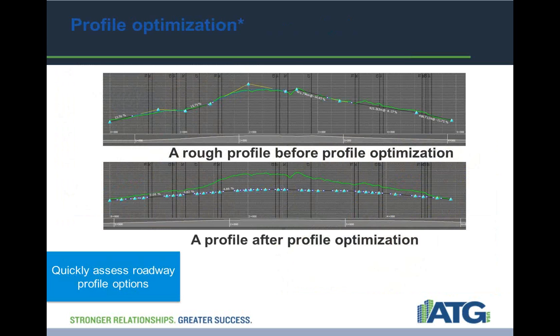You can use the profile optimization for Infraworks 360 to engineer a road's optimal vertical path based on parameters you define. After adding a design road, to engineer its optimal profile, you can generate several optimization jobs, each using a different combination of design speed and advanced settings.